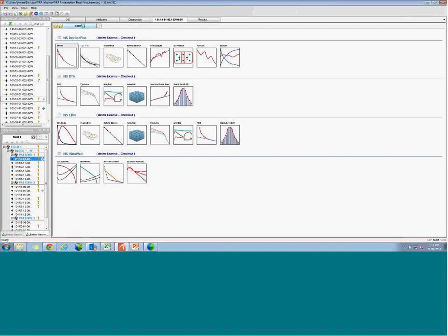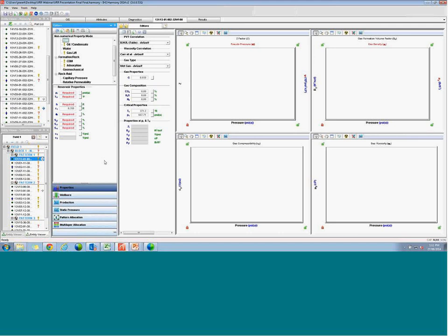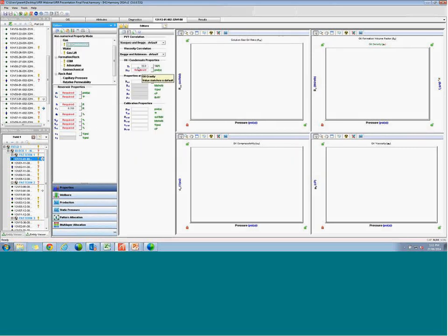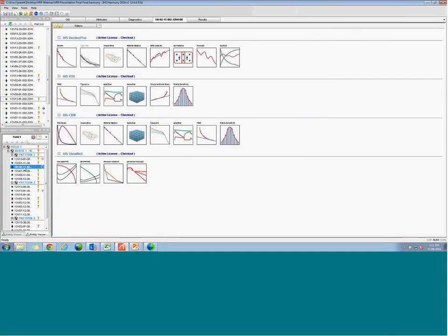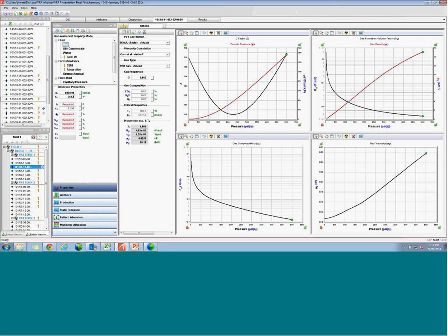Now let's look at the producing wells here, and click on them to show the properties. What you'll note here is I have not populated any of the reservoir properties into this well. I have some default PVT data, such as gas gravity and oil gravity. Those are all defaults; I didn't add any information into there. For the injector well, information was input, and the information that I put in was initial pressure and reservoir temperature. And I also have a gas gravity, which is not required, but you'll see what that is in a second.